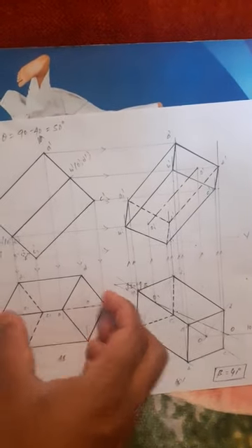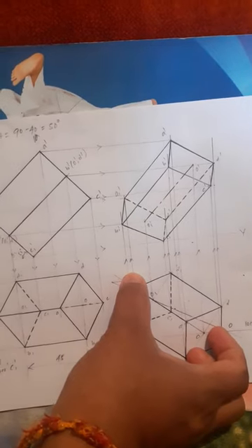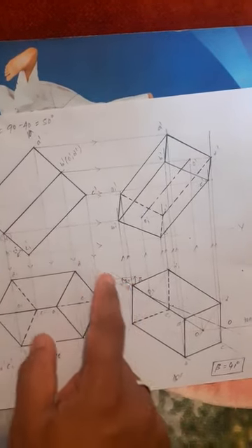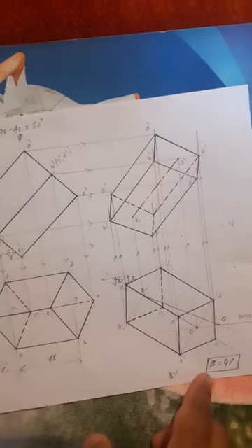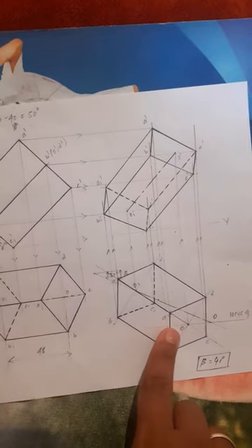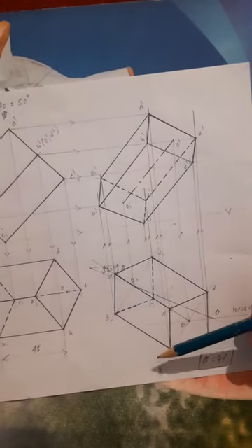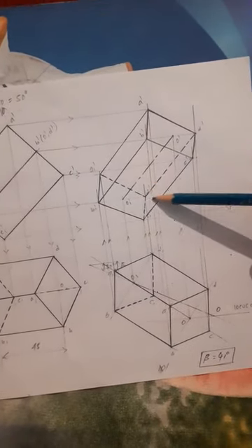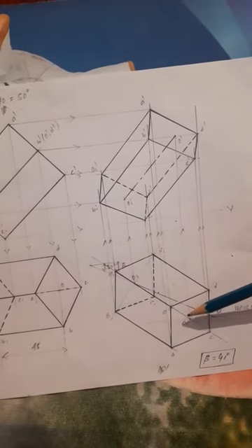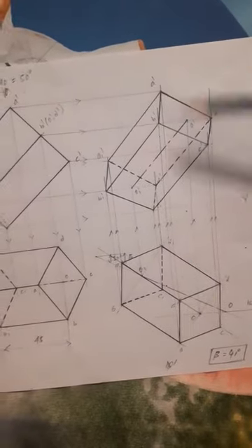Now, as you know, all outlines are visible. You transfer these solids onto the beta degree line. Measure the extended beta degree line. If you measure it, how much will you get? You will get 41 degrees. That completes the third position top view. Now project all the corners to get the third position front view. Project all the corners of the base and the top face vertically upward.